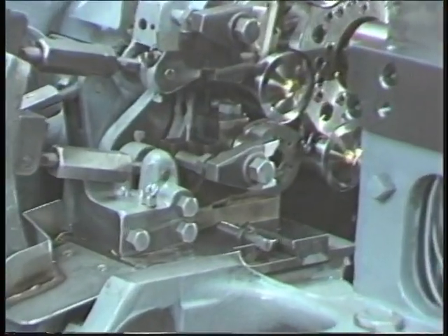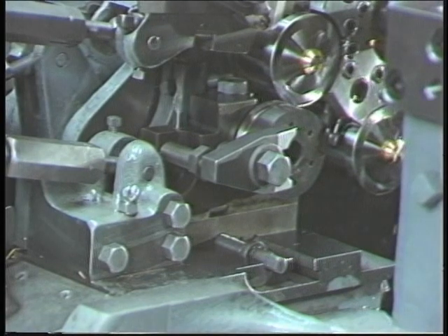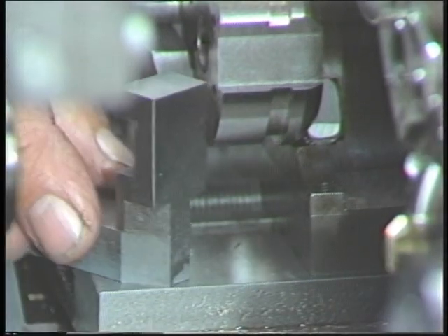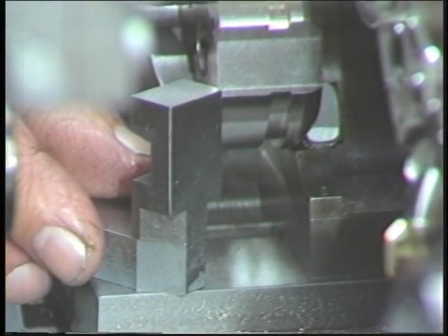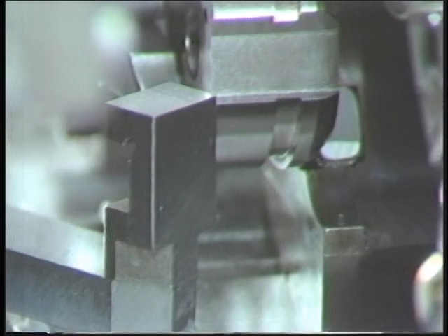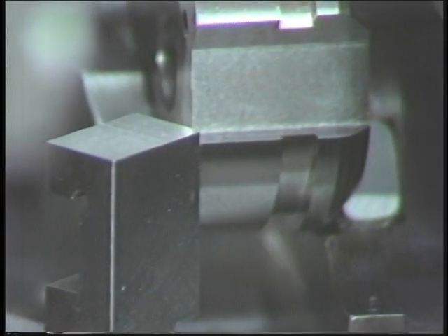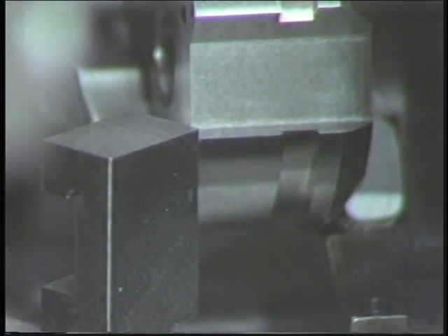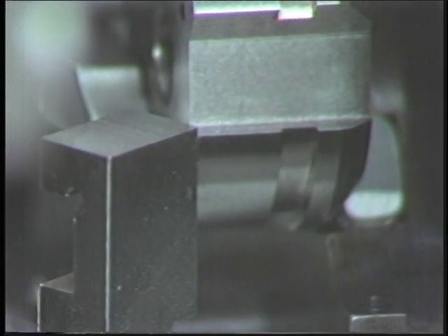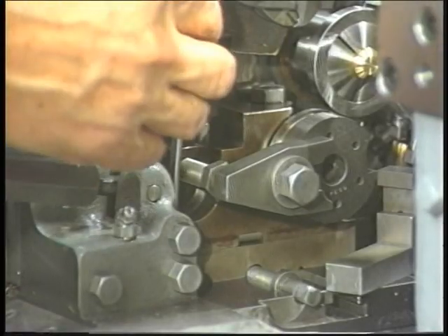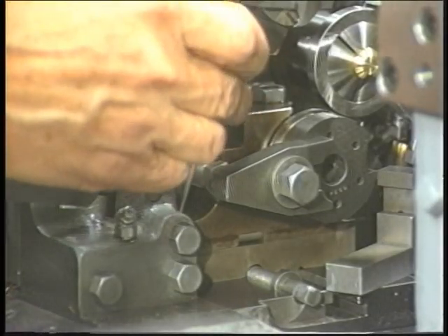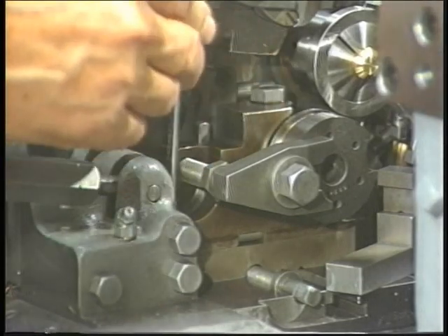Once the tool has been inserted and snugged up, bring it to center by following these instructions. Put the tool setting block on the first position cross slide. Be sure the tool setting block is close to the cutting edge of the tool. Bring the tool up to center by turning the height adjusting worm counterclockwise until the tool is even with the top of the tool setting block.